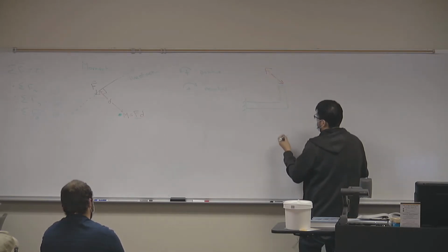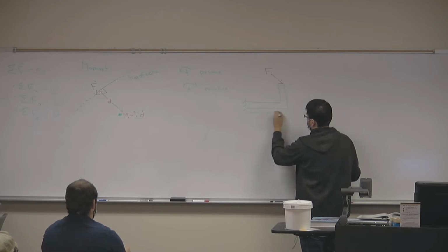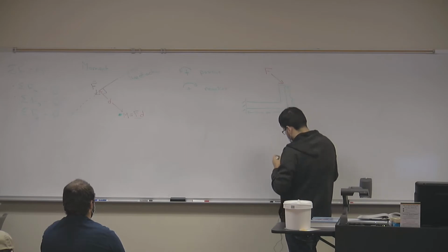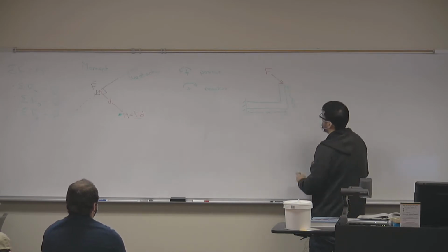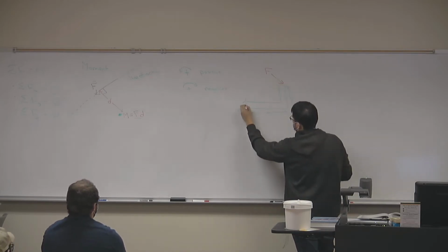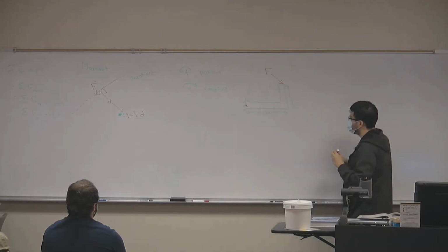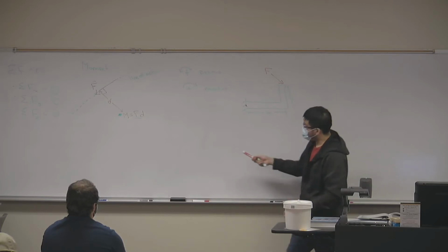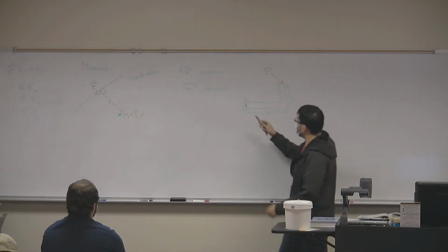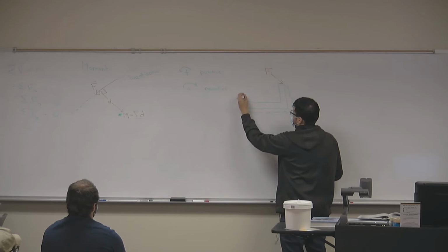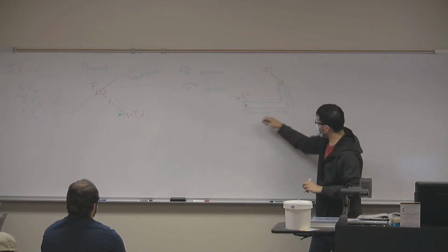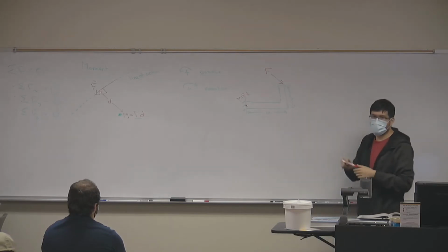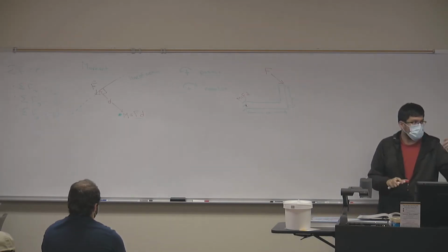And I have this distance, I'm just going to call it A. And this distance, I'm going to call it B. If I want the moment, the tendency of rotation that this force causes about this point, what will my distance D be? What would this D be in order to calculate moment? Moment equals F times D. So what is D? Is D equal to A plus B? No. So what would D be equal to given this information? The square root of A squared plus B squared.